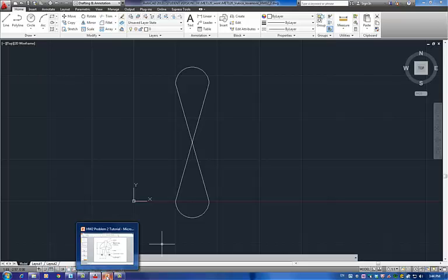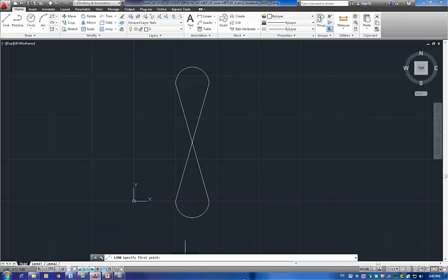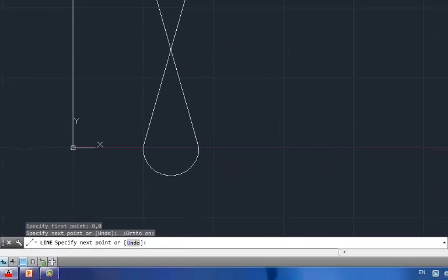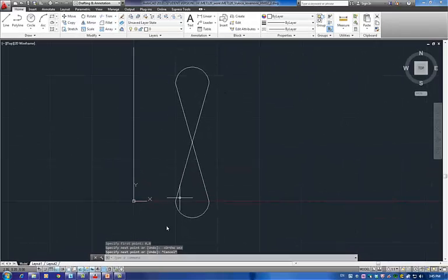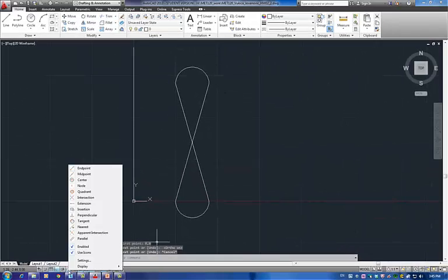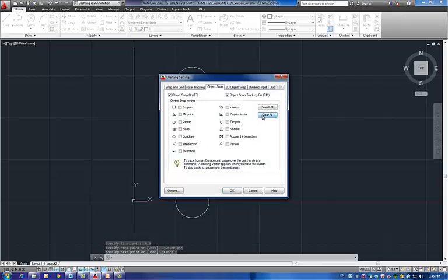So one way is what I show you in class. I can create a line that starts with 0, 0, and then I will turn ortho, and it will just go somewhere above with this ortho option. You see, now it's either horizontal or vertical, so I will use the vertical. It doesn't matter how big that is. I will just click somewhere, and then I will use the snapping tool, settings, clear.